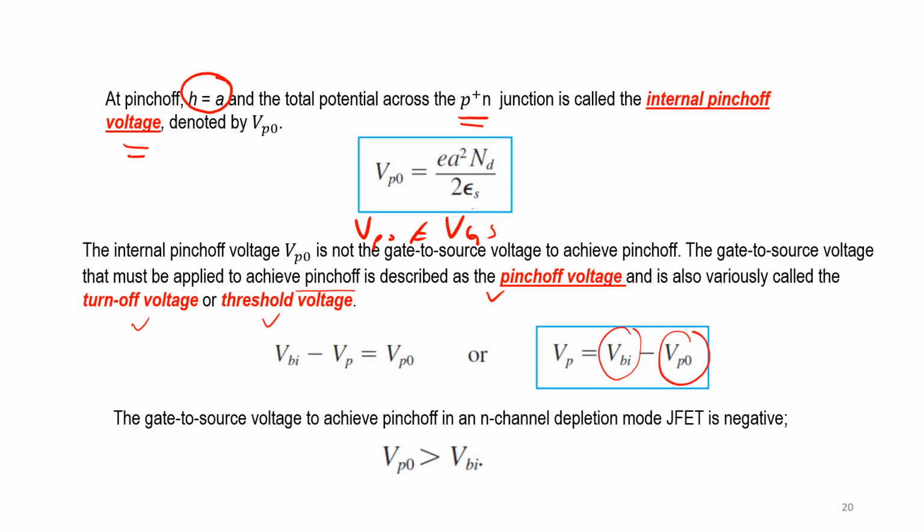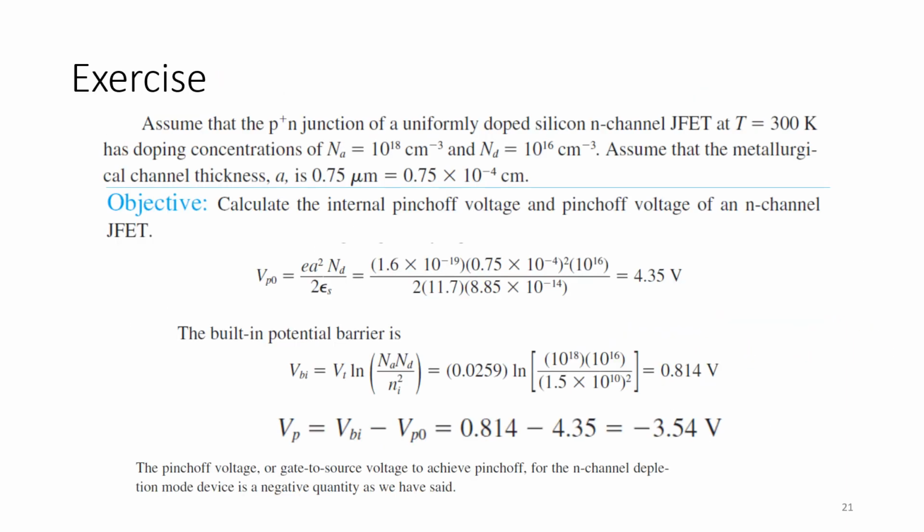In terms of MESFET operation, the pinch-off voltage is known as the threshold voltage. So the threshold voltage is also equal to VBI minus VPO.